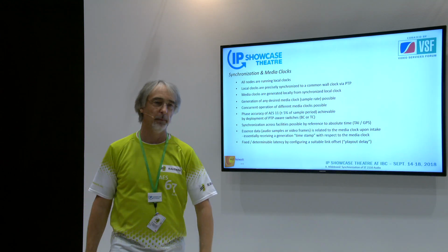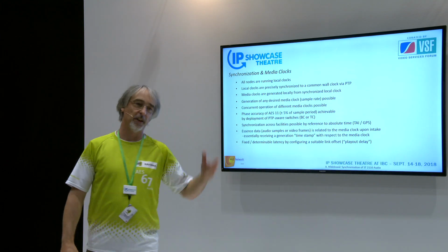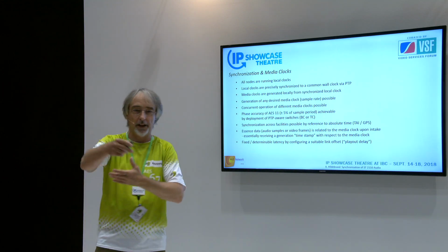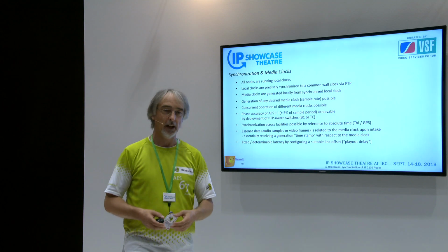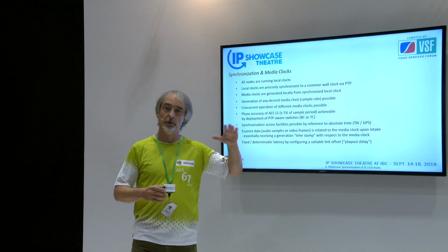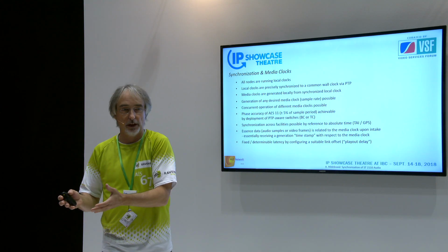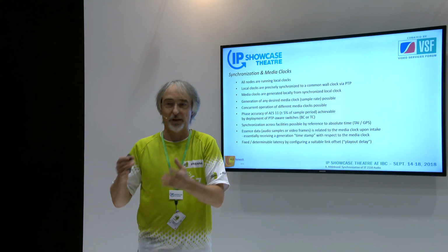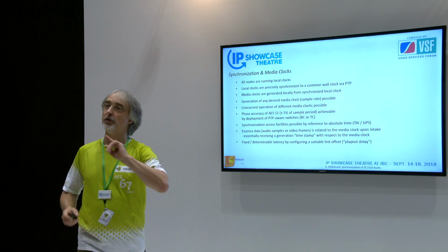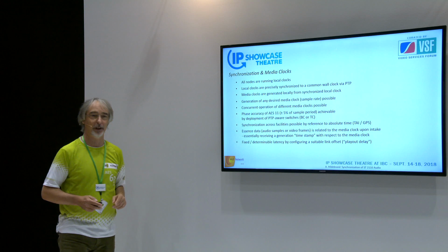I can use a 50 millisecond processing delay because there might be more switch stages in between, or it might have to correlate with any other ambience or process signal, and so on. So particularly, one single stream can be received wherever it needs to be received with individually suitable, appropriate latencies. Only if I want to correlate streams, now this is the tricky part.